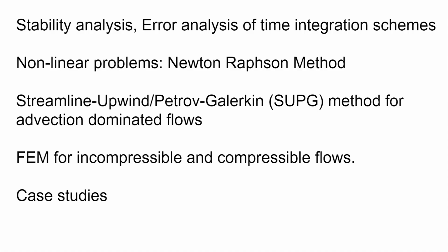Once we are ready with this, we are actually ready to go into fluid mechanics. As I said earlier, the traditional finite element method gives some problems with fluid mechanics problems. So, how do you get around them? We will talk about the so called SUPG method, the streamlined upwind Petrov-Galerkin method. It has some parallels with finite difference methods which are upwinded.